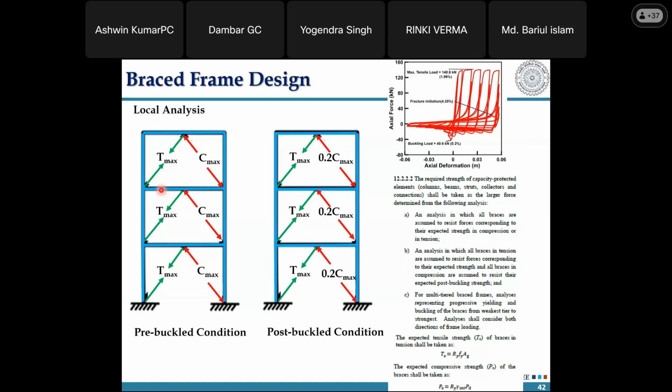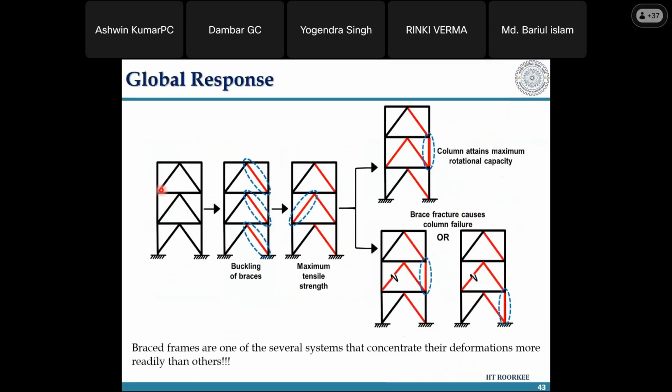So the residual interstory drift ratio is the main negative for a BRBF system, right? Once you design, yes, you have to look at the residual interstory drift ratio specifically if you are designing a BRBF system. But if you are doing a CBF system, yes, more residual deformation is not better, but that particular residual interstory drift ratio is not a problem for a CBF system.